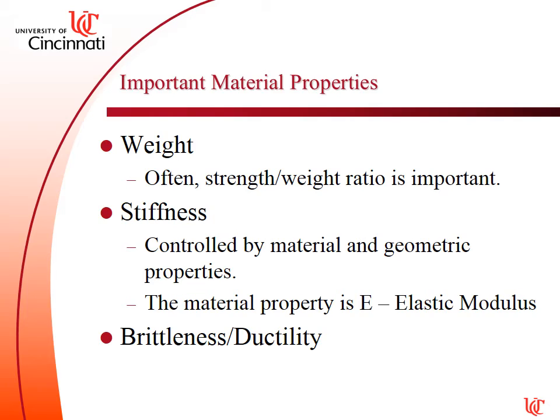If you remember back to statics and strength of materials, we talked about the moment of inertia, and how it related to a material's stiffness relative to bending. So a shape with a high moment of inertia, a larger portion of geometric area, is going to be stiffer.